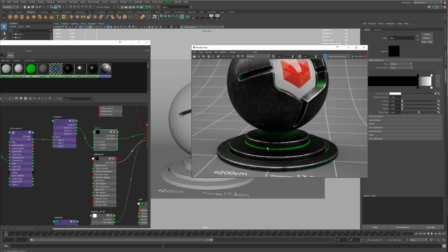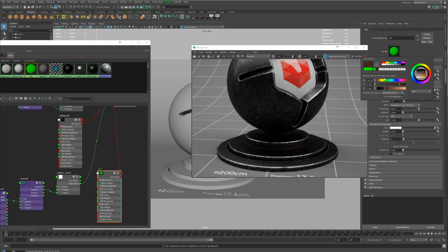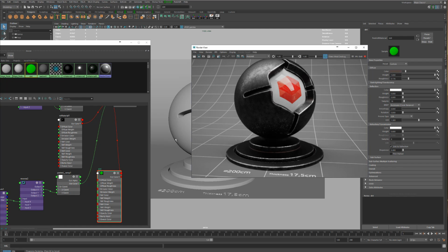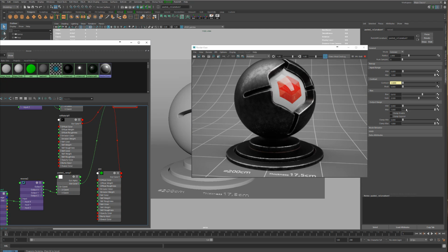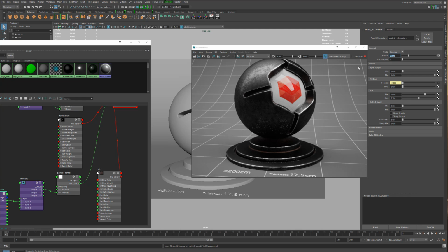And so now that we've got this, let's turn that color into actual dirt, something brown. Let's go with something a little lighter, less saturated. And let's actually spread that out over the surface a little more too. So let's increase the bias and tweak the ramp. Let's push that ramp down. Let's spread this to 3.